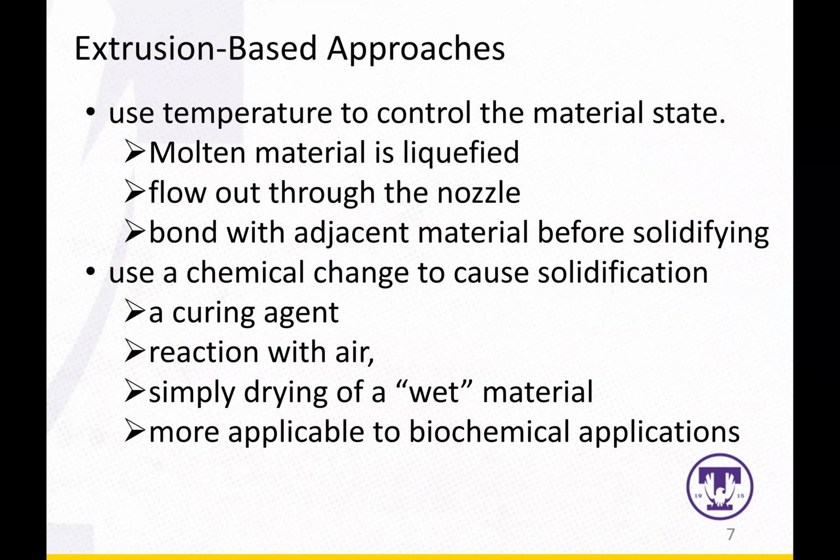So basically, there are some important points for the extrusion-based approach. First of all, it uses temperature to control the material state. The thermoplastic will be liquefied, and then it flows out through the nozzle. And then the material bonds with the adjacent material before solidifying, right?